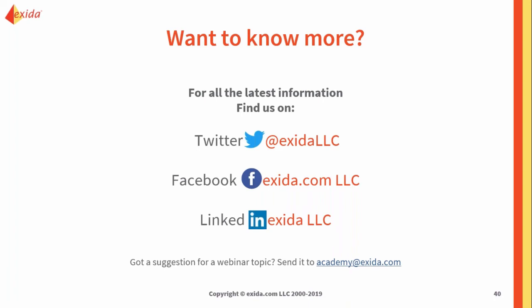Okay, the next question is about some of those databases that we were talking about, such as the FMEDA database and the B10 database. The B10 database isn't necessarily a database per se. That's more of a testing done on pieces of equipment, an analysis done from that. The FMEDA database, I can talk to the one that exida uses. We have a calibrated FMEDA database. We are continuously updating it, and we actually do publish our components. It's in our tools for everybody to see and use.